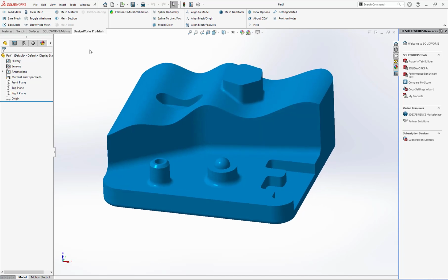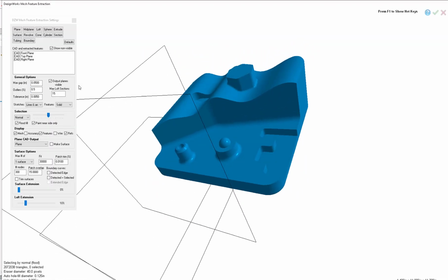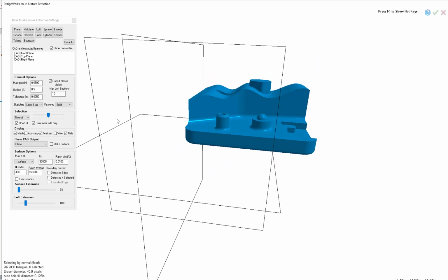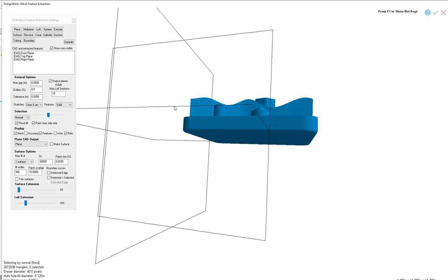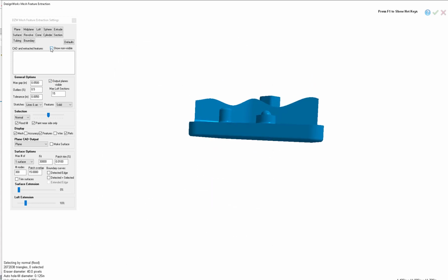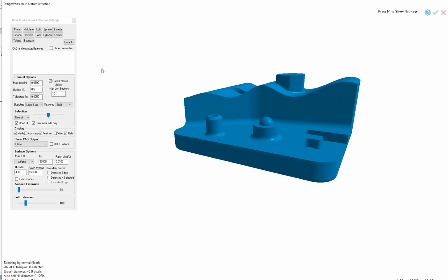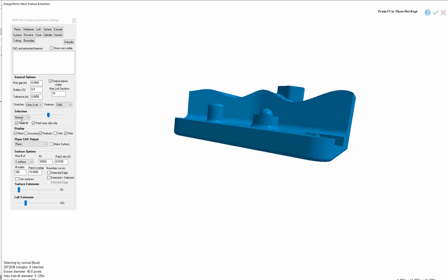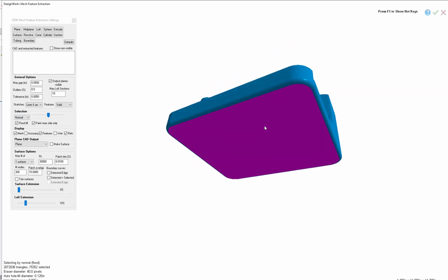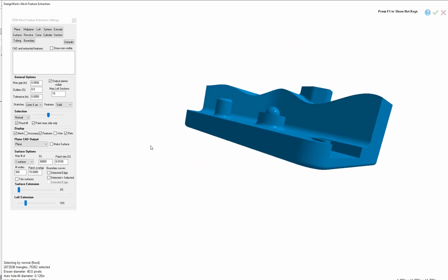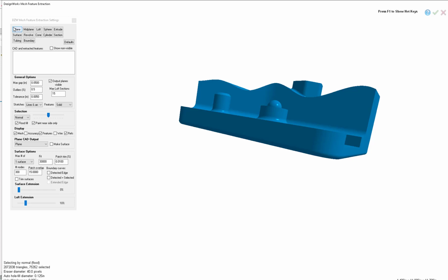So if I'm using mesh features, I'll select the mesh features tool. And we normally build this. We'd go ahead and we'd paint the bottom. And the reason why I paint the bottom, we're going to constrain it to a plane. Let's turn off these non-visible. So we're going to be using the normal painting. And we're going to click on the bottom, left click. So it identifies something here. And if I want to make this a plane, I can make it a plane or make it a surface plane. I'm going to just make it a plane.